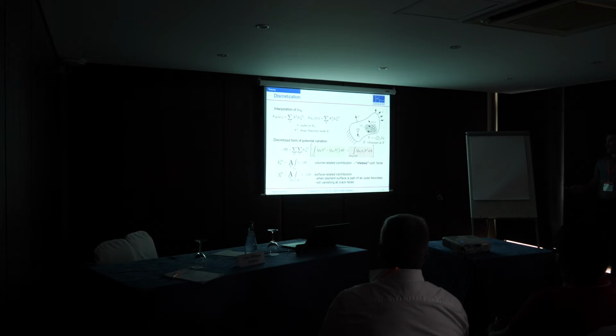We have our shape function and our mechanical fields. This is very nice, but this part is not very nice. It is quite hard to evaluate because when we want to calculate the driving force for a crack tip or a point on the crack front, the mechanical fields involved in this part are very poorly represented in the finite element method. So we do not want to calculate this, but we want to evaluate accurate driving forces, so we have to circumvent the calculation of this.